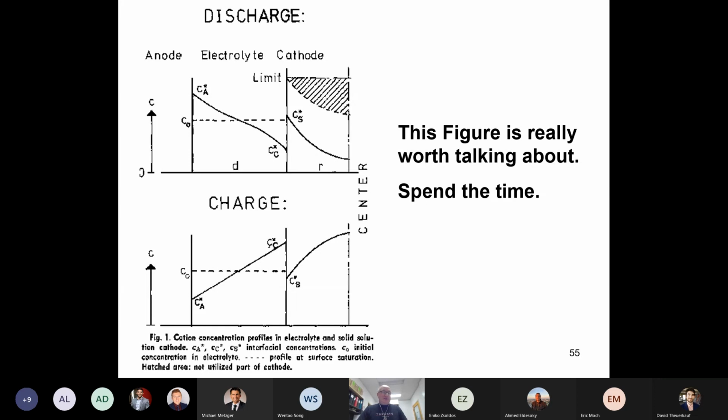And that's why we don't use electrode material particles that are 50 microns in diameter or 100 microns in diameter. We keep them pretty small. And the electrolyte transport lengths, from one side of the anode to the other side of the cathode nowadays, is on the order of 150 micrometers. So much, much bigger than the diameter of a particle, more like 10. And it's because of that diffusion constant difference that that's the case.